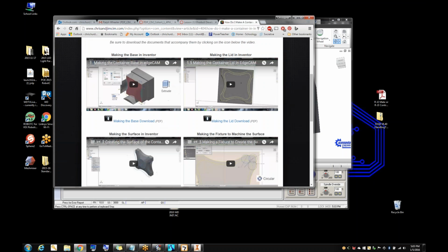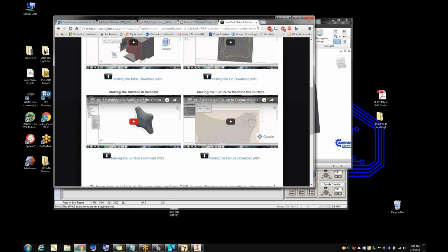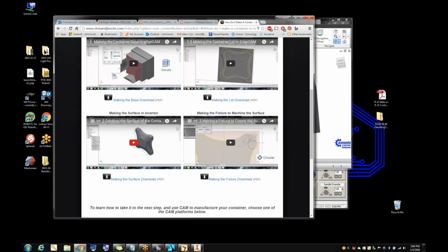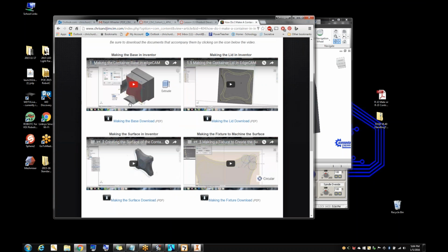I utilized. The only thing, and I don't remember which mill you have, the big deal is the Benchman and the Pro mill. They're two new ones. 3/8 of an inch is the largest shank that they have. So the tool I'm using, I think in the video, I don't remember if I backed it off to a 3/8 of an inch or if I kept it with my 1/2 inch. But regardless, whatever tool you've got, you can kind of change my numbers to fit whatever you've got.